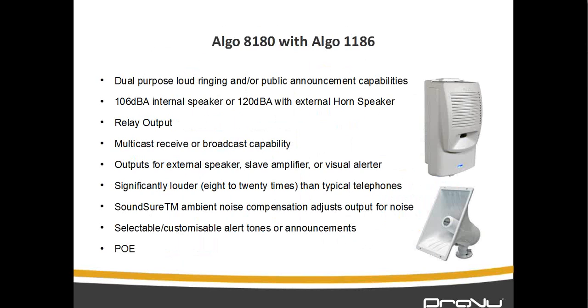And most commonly, it is PoE. So you can just hook it up to a network switch, PoE enabled switch, and it will power, and you access it from your web browser and configure it. Again, the announcements or the ringtones or alert tunes are customizable. So if you want to upload your own, you can do that as well. Now, there is a limited memory available on the actual system, which is about 3 meg. But if you do want more than 3 meg worth of audio files, what you do is basically delete all unnecessary files already there.